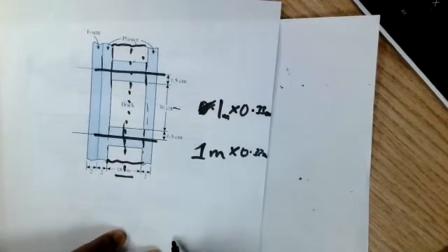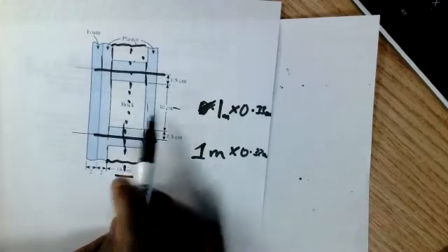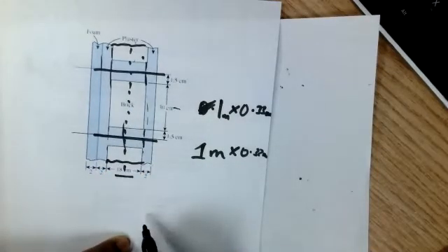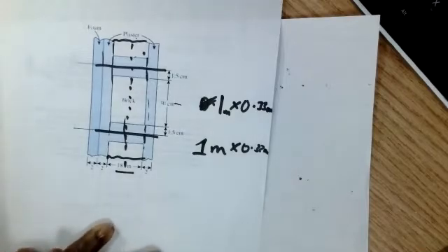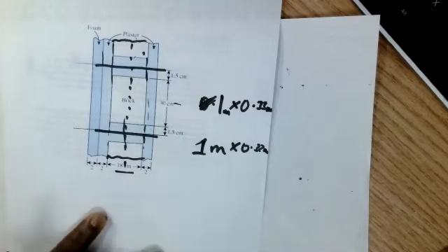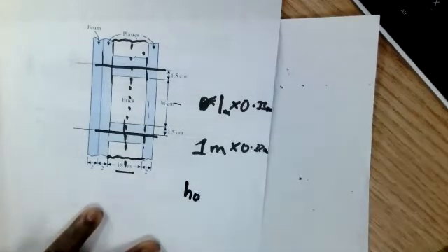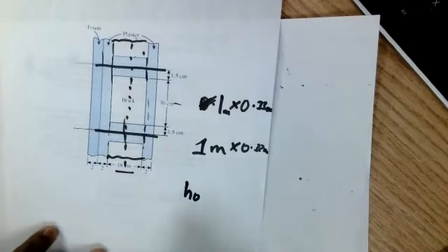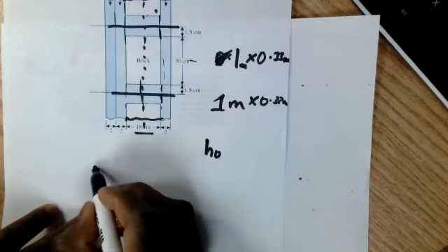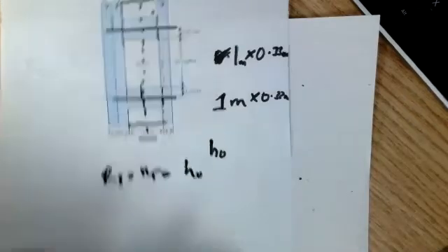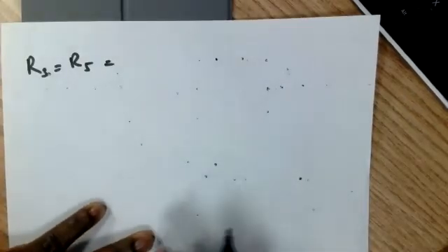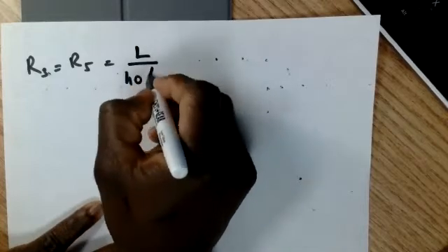Now, if you balance out the thermal conductivities through this wall, they kind of depend on each other. Okay, so instead of dividing this by the thermal conductivity K, we'll divide it by H outside. I hope that makes sense to you. So R3 and R5 will depend on H outside. Okay. So in our expression, we're going to have L over H outside multiplied by A.